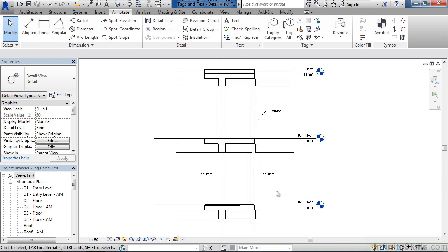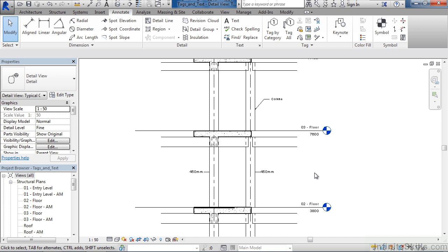The size of the text in the arrows, even though set based on the font that we used, is also controlled by the view scale. So as you change the scale, making it larger or smaller for the view, this text and the arrows will size appropriately when placed on a sheet.